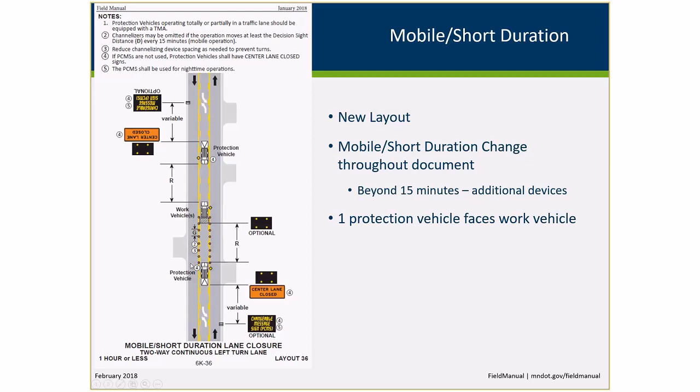And this provides a lot more positive guidance for drivers that are navigating this so that they don't cut into the work area past a protection vehicle. The channelizing devices really direct the drivers to go around that area, and that improves the safety for the workers. So just something to be aware of.